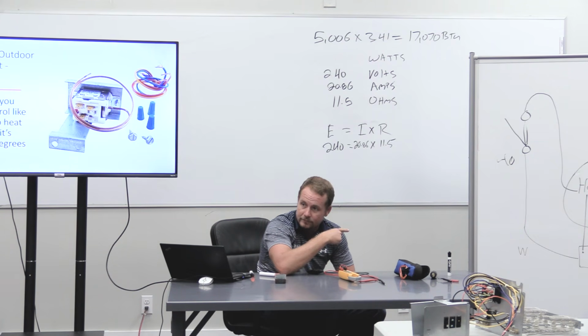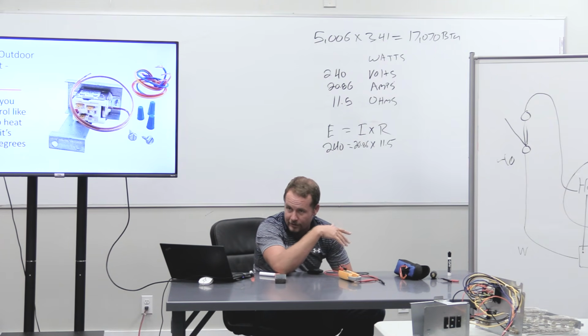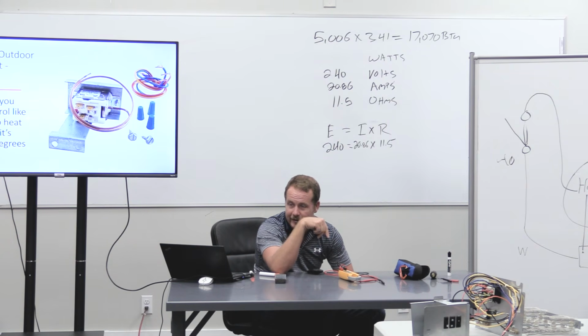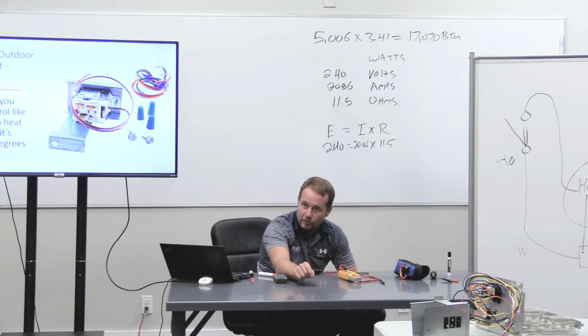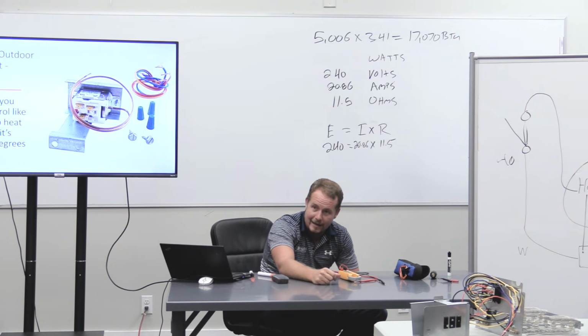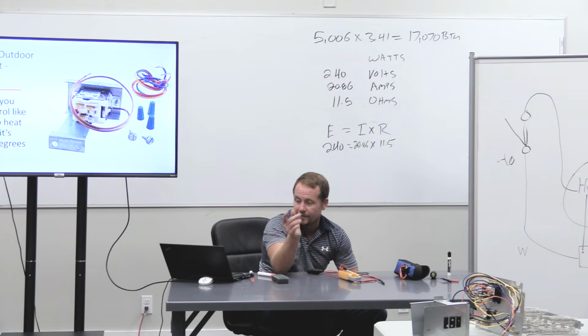Then that's going out, and you're running another wire, black, brown, green, whatever extra you want to use, back from the condenser to the air handler, and that one is what you're connecting to the air handler white. So the air handler white is only being connected from that wire coming from the outside. And so unless that closes, it's not going to allow it. And in fact, you could actually wire it in such a way that it would work the way this code says.